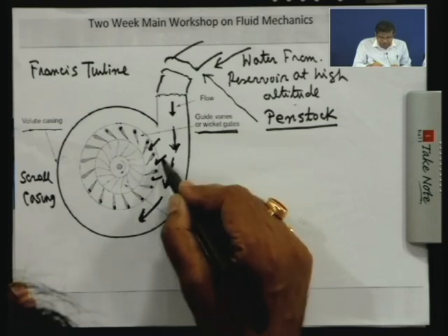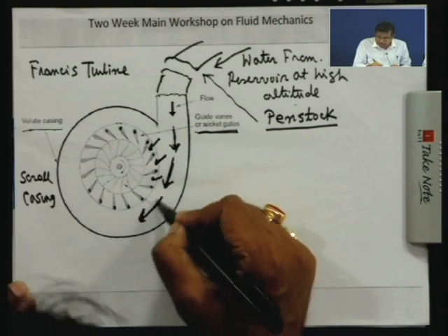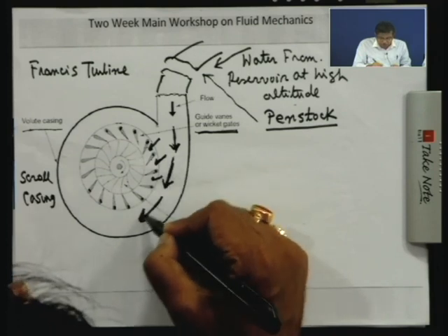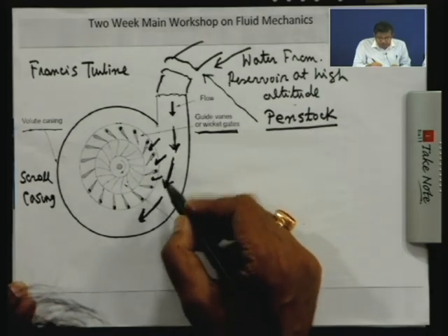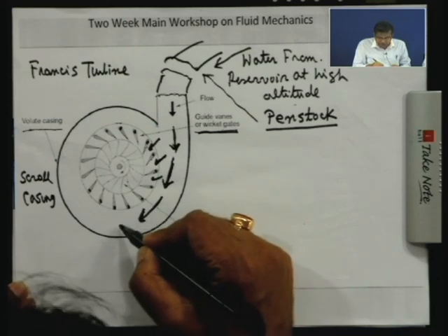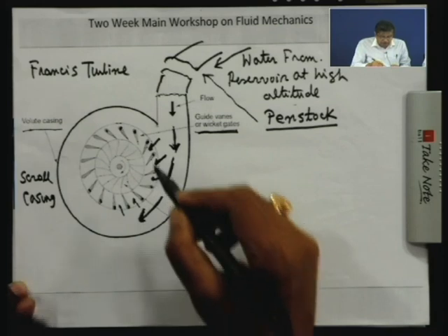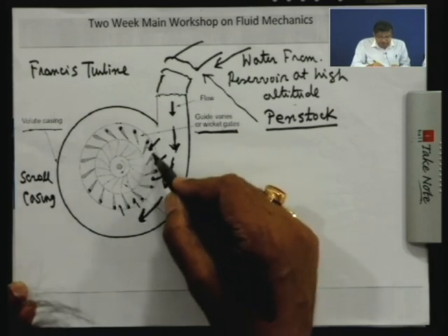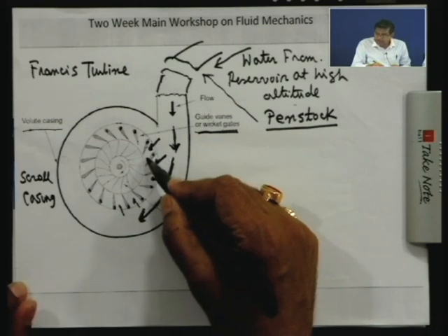Well, because the flow is entering here. So, if we have to maintain the velocity constant throughout this passage of flow, we have to reduce the area in proportion, so that velocity remains constant. And the constancy of velocity is to give a smooth entry to this passage. Now, this passage formed by these stationary guide vanes is a converging passage. That means it is similar to a nozzle. So, what does a converging passage do? It increases the velocity and decreases the pressure.